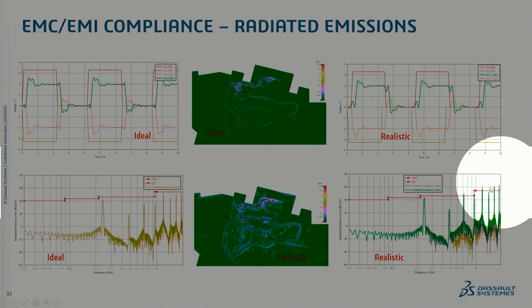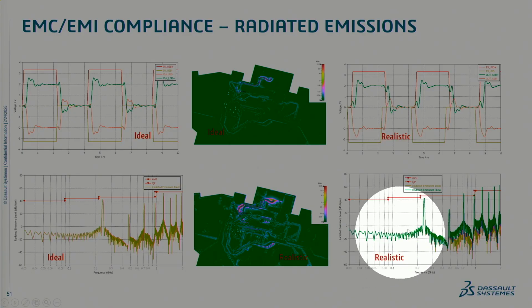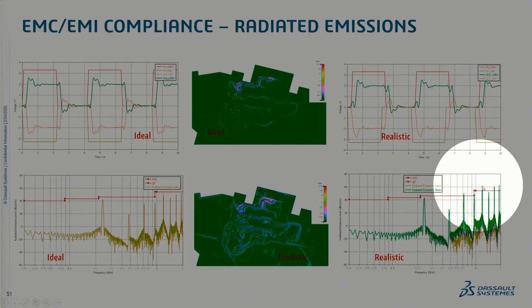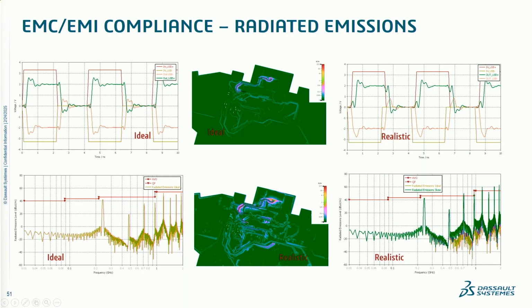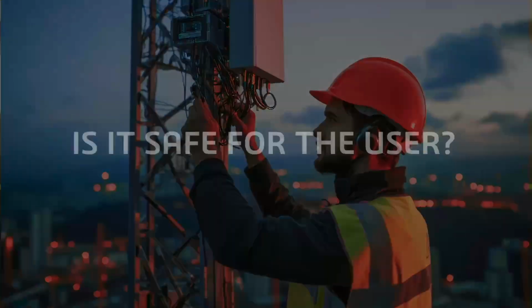Anywhere we exceed that line, and this is over the frequency spectrum, guys, on a log scale, but anywhere we exceed that, even one of those would fail that test for us. So this is the type of analysis we need to do to find out if we're going to pass compliance testing. And why? Because if you fail it, you're going to delay your launch. You're looking at months of redesign. So that's the regulatory side of compliance.